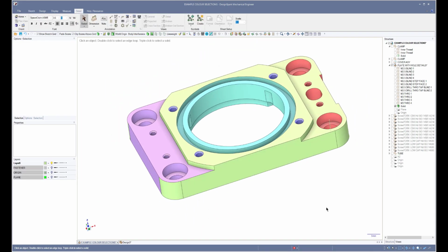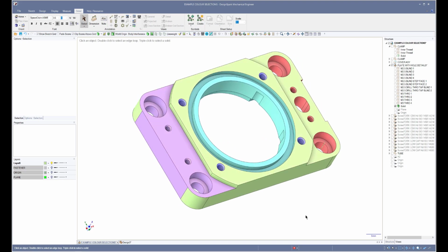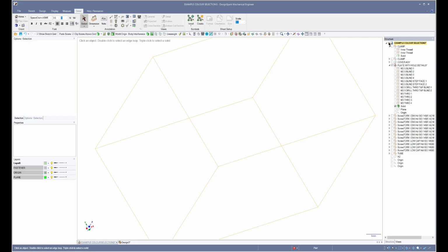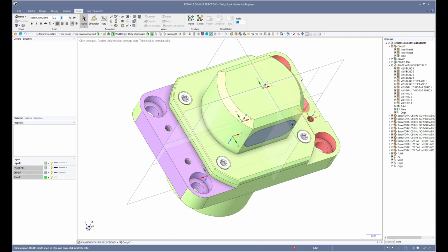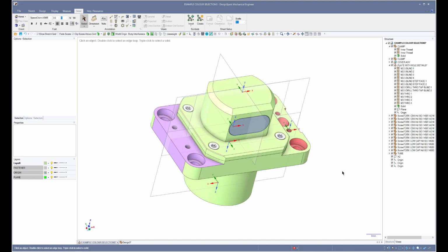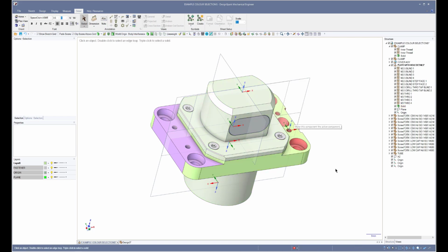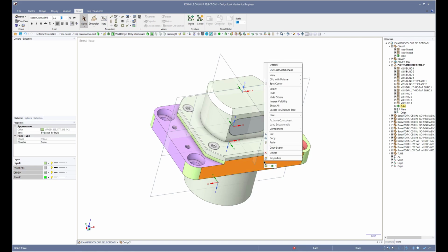So if we now consider just this plate, but perhaps we want to show some more qualified measuring information, I'm just firstly going to show everything in terms of what we've got for this particular item. Okay, so we turn off the full assembly, turn it back on, and we have everything on. Let's ensure that we only have the correct part as active. We will right click, activate component. We'll right click again, show only, hide others rather.